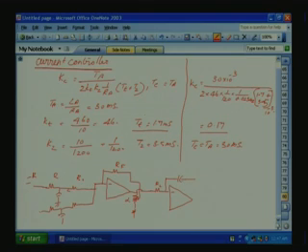see integral time constant, we know Tn is equal to Tc is equal to Ts 30 milliseconds. So, Rc we can choose it that way. Okay. Then how to adjust fine tuning? Fine tuning you can do it again here like this with a potentiometer here and with a small resistance here, so that we should not short it while controlling. Okay, alpha you can control. This will take care of our Tc. This will take care of our Kc, and this is the adjustment.